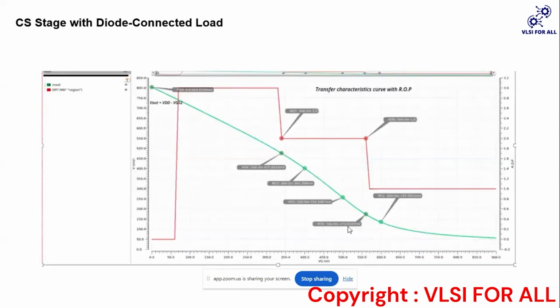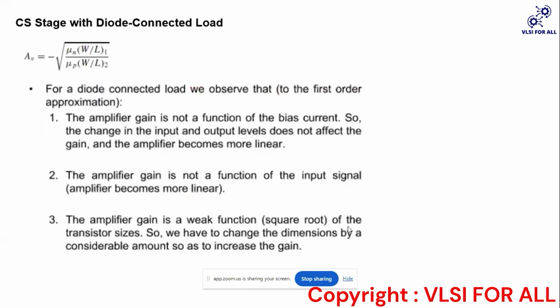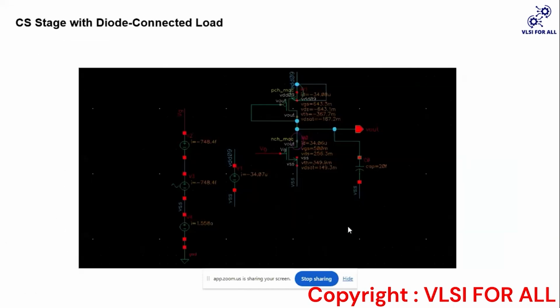So what will be the gain of this circuit? Okay, what will be the gain of this circuit? So let me find from here. For finding the gain, what do we do, right? We deactivate the DC source. We only apply the AC source. Okay, we replace the ideal current source or ideal voltage source with its intrinsic impedance. Like for an ideal current source, it will be open circuited, and an ideal voltage source, it will be short circuited.